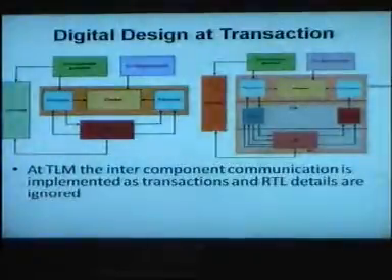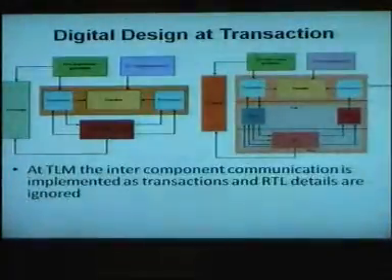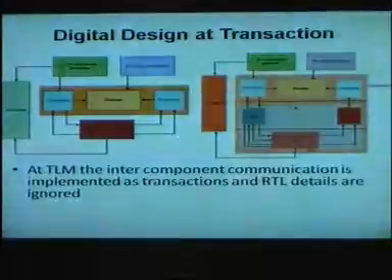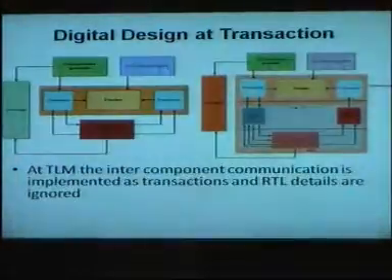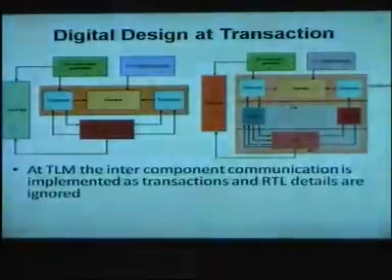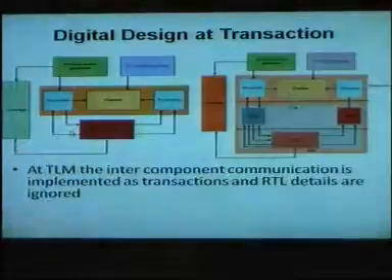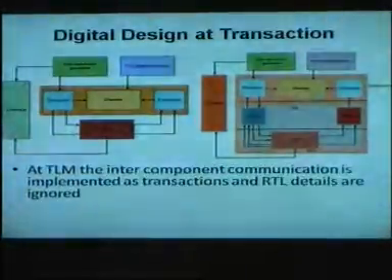So you do transaction level modeling so that you focus more on the actual algorithms. At the same time, there are people who are trying to make the interface work, the RTL and the actual coding. As you can see, there are only two lines which show you put something in the device and you take something from the device at the transaction level.